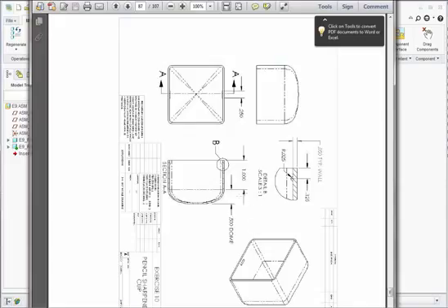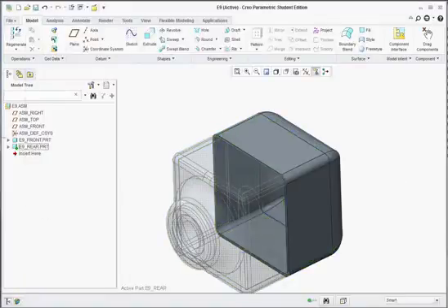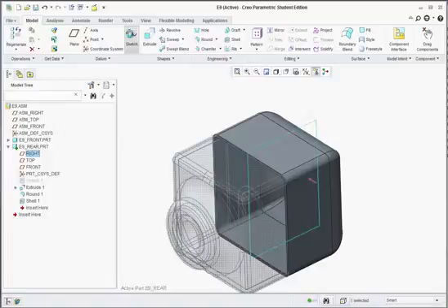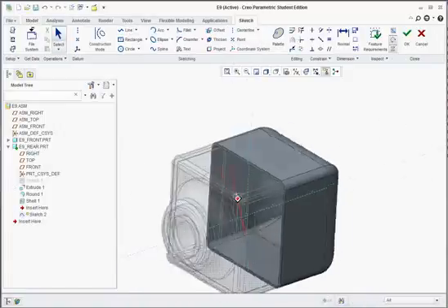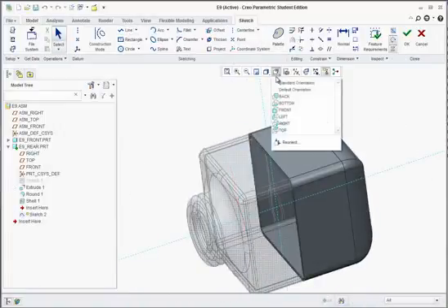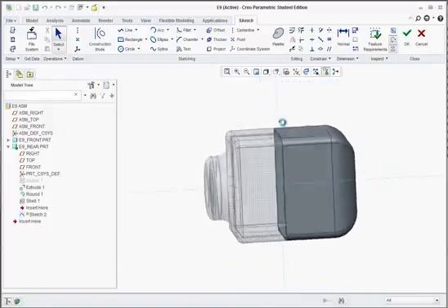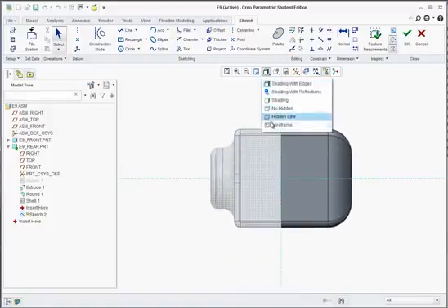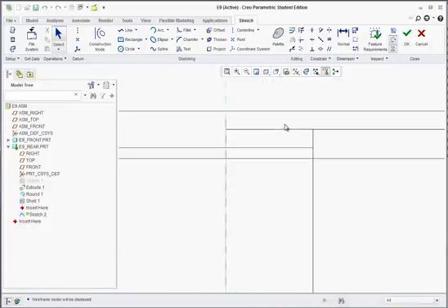Now there's a little detail of these clip mechanisms that need to be put in here. So let's go ahead and put one of those in. They have to be on both sides. They're symmetric. They're centered. I should say it's 0.125 off the front edge. So what we can do for that is hit the little arrow to the right of E9 rear and select the right plane and start a sketch on it. That's right in the center, as you can see here. Now we could actually go here to right and then also change it to wireframe and zoom up.